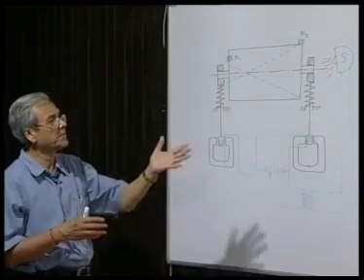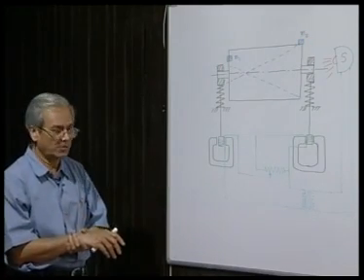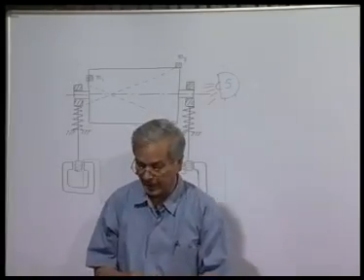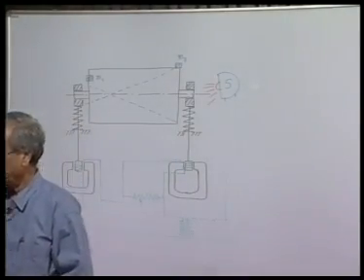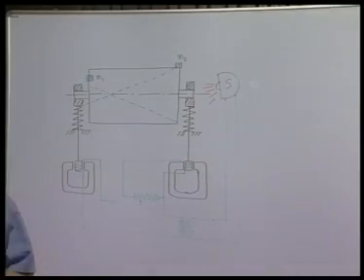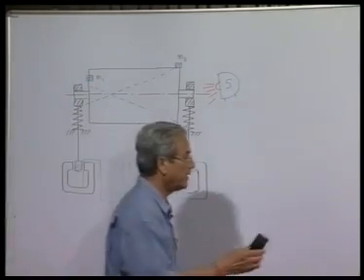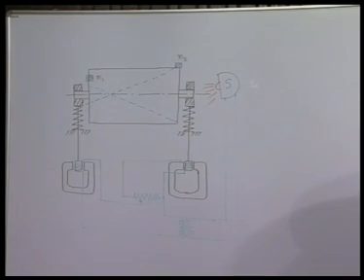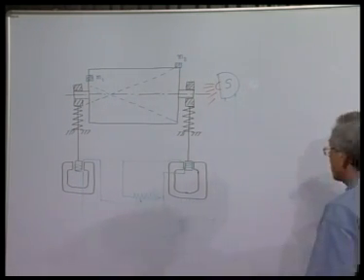So, these are the principles of balancing machines which are used for balancing actual rotors when they are not very large. Now, let us consider the case where the rotors are very large and you cannot bring them to your lab to put on balancing machines, like a turbine rotor or a huge industrial fan.